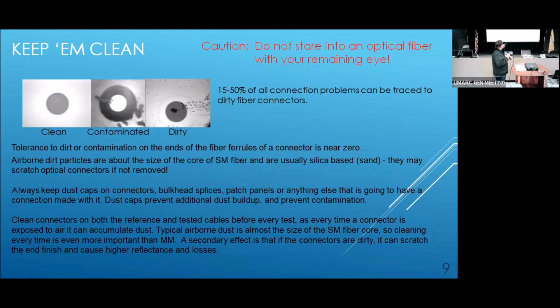So always keep dust caps on the connectors and anything else that's going to have a connection. Try to prevent dust, and always check your fibers for dust. They have fiber optic microscopes that you put the bare fiber into, and you can actually see the dust, and you can tell if your cleaning method is effective. One other very important point, on the top right, it says, caution, do not stare into a fiber with your remaining eye. Yeah, watch out for that one. Okay, next slide, please.